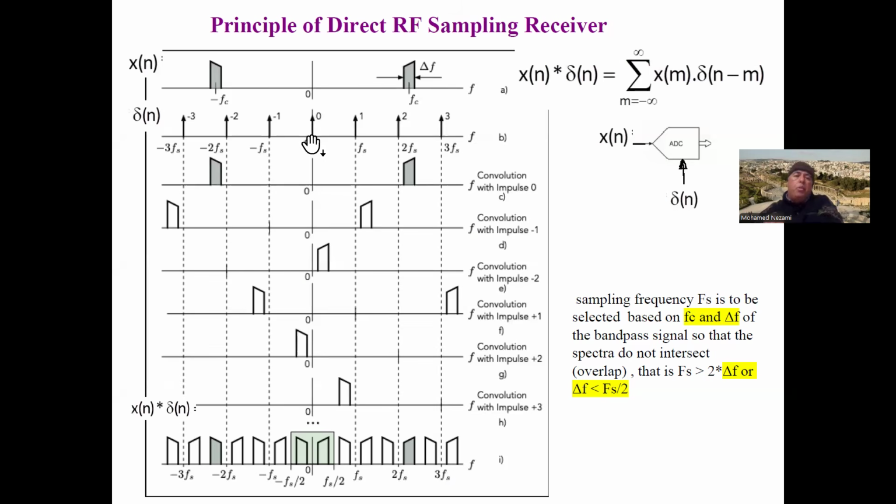So when you convolve this with this, it's splitting this summation into individual points for the M indices in here. And the M indices are 0, 1, 2, 3, and so forth, which are the harmonics of the Fs. And then you also have the negative image of that operating on here.